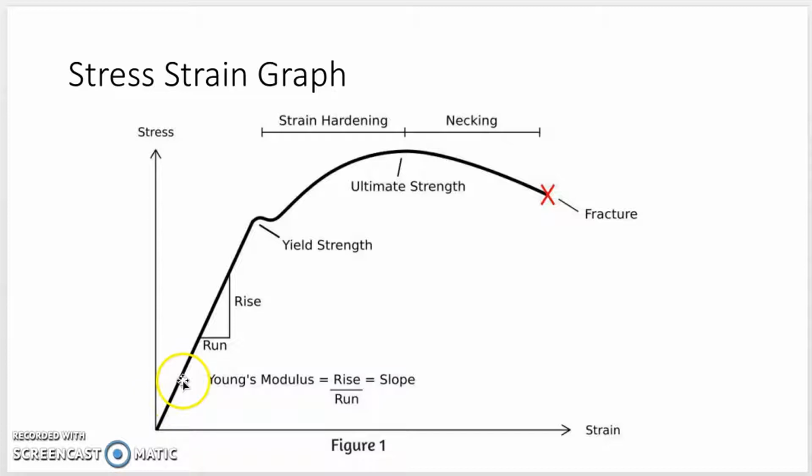But if you push that same piece of metal past this point, which is its yield strength, it'll start to plastically deform, which means that when you let that force go, it will not bounce back to its original shape. And this is where you enter the strain hardening region, which is what we were doing when we were going through the cold working process earlier.